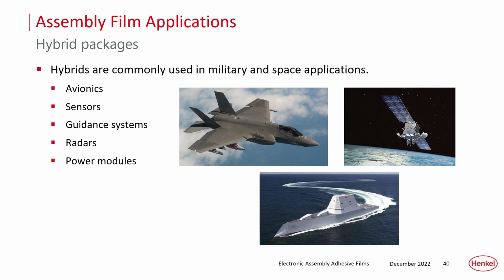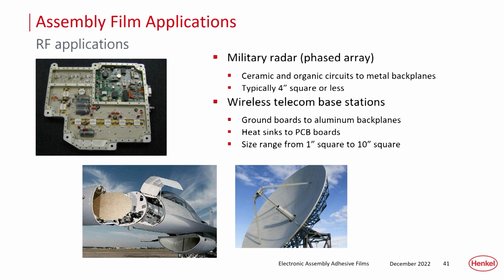Okay, next one. And again, a few pictures showing use in high frequency applications, both military radar systems, but also increasingly in wireless telecom base stations, where boards are being bonded onto metal backplanes. And those can be sizes up to about 6 by 4 inches, 150 by 100 millimeters, and giving perfectly adequate reliability.